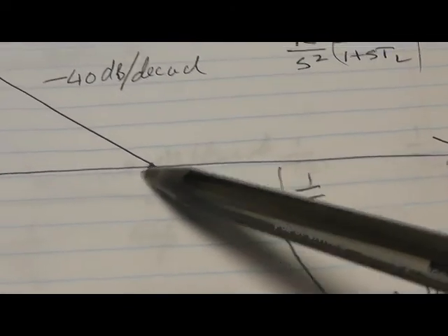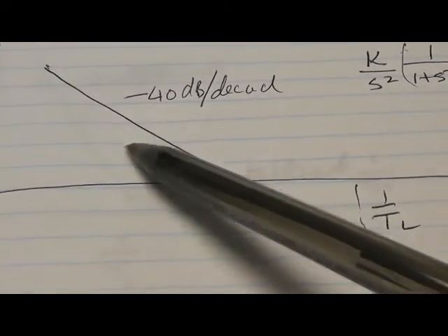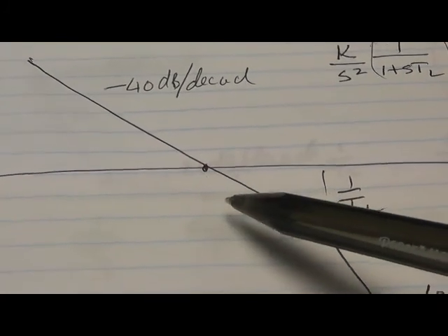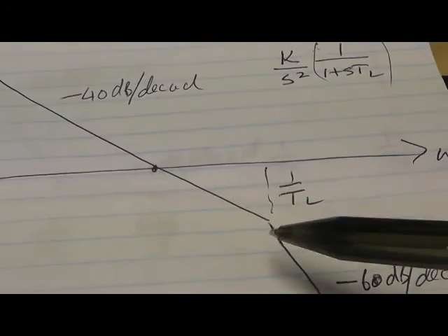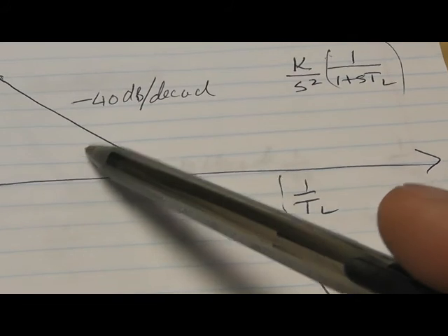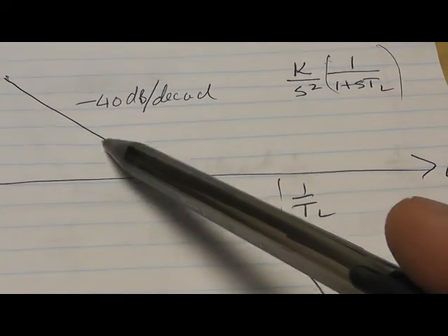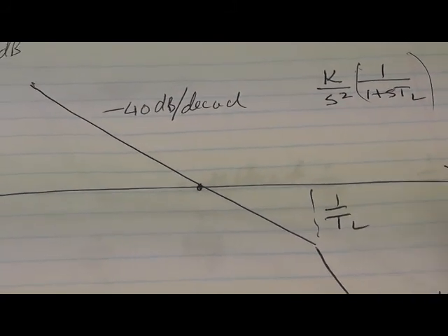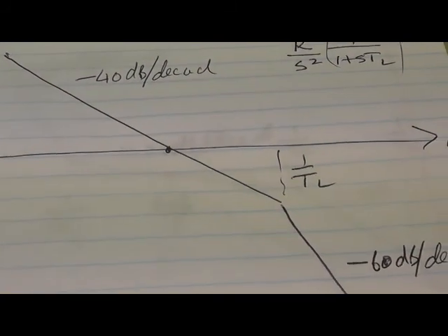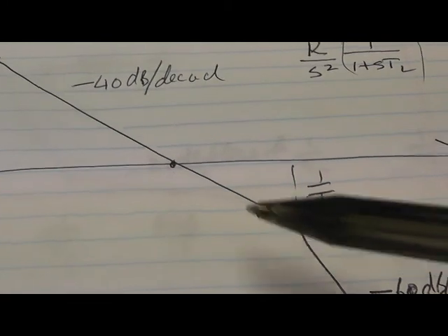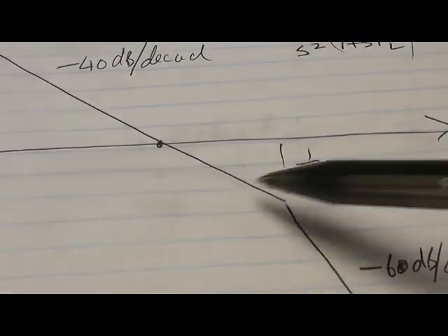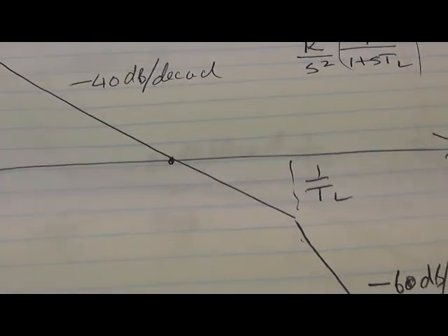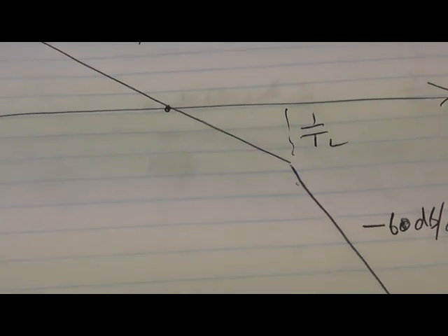So we can put this in here somewhere. We could kind of put it in there, or we could put it anywhere really, depending on what bandwidth we're looking for. Kind of looks convenient. We might just even need one 0, but you can't really put 1 0 in on its own. You kind of need the pole with the 0 because it's physically unrealizable to have a 0 on its own. So we'll put it in somewhere here, and we'll leave this pole just to attenuate the high frequencies.